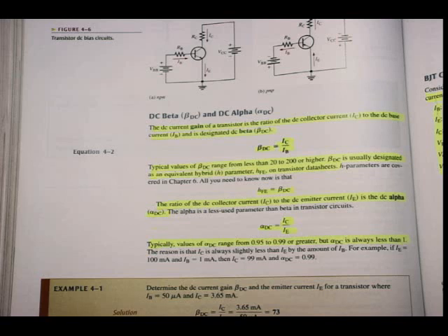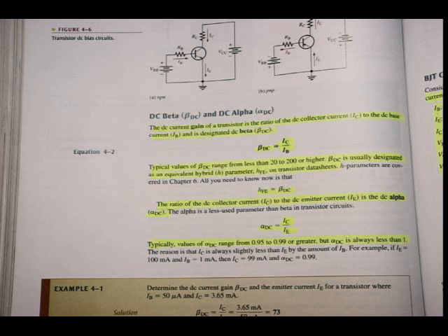But what I can see is that the value of beta DC is normally a large value. Why is it a large value? I can check it. What have I learned about the currents? I've learned that IE is the largest current because it adds IB and IC. But when we've discussed the operation of a transistor, how does it amplify? What we've seen: emitter, highly doped, big; base material, thin, lightly doped. So what's going to happen? A little bit of recombination.